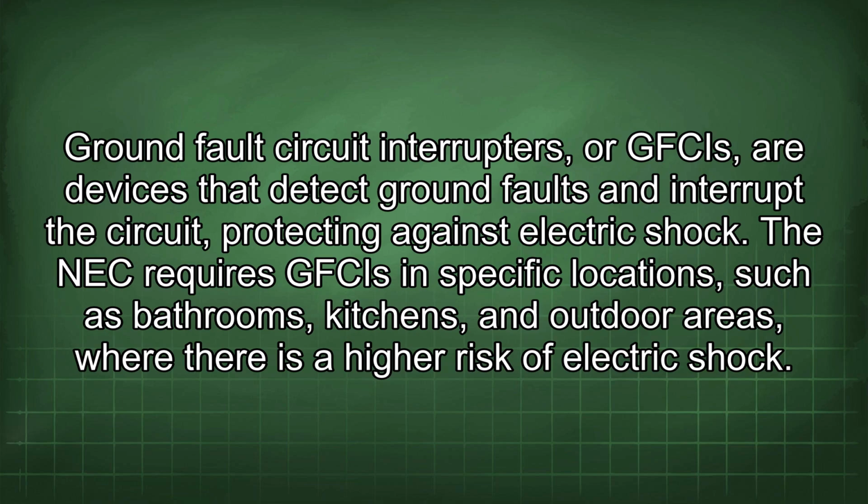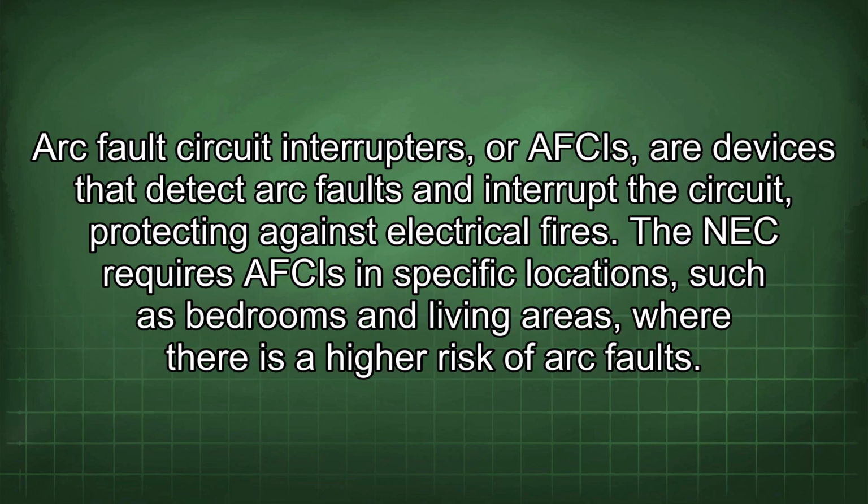risk of electric shock. Arc fault circuit interrupters, or AFCIs, are devices that detect arc faults and interrupt the circuit, protecting against electrical fires. The NEC requires AFCIs in specific locations, such as bedrooms and living areas, where there is a higher risk of arc faults.